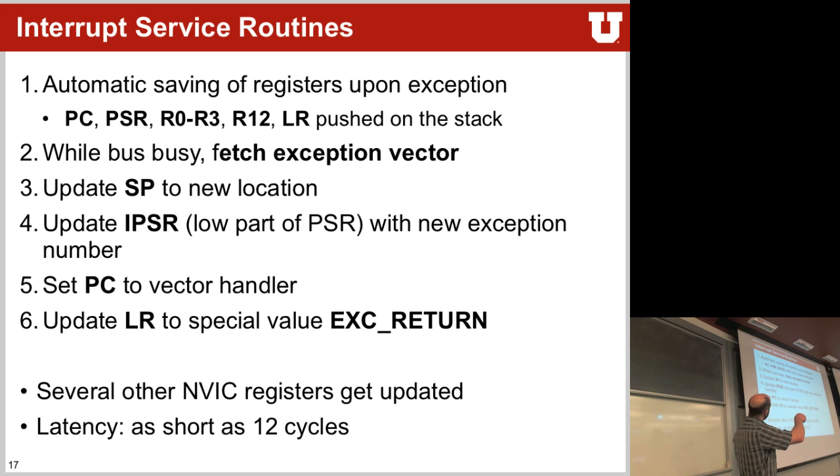First of all, if you look at this sequence, the stack pointer gets updated, but we also store the stack pointer. Same with the PC, right? What about the status? We also update the status. So we can do stuff here in parallel. If we start writing certain things before others, we can do things concurrently.